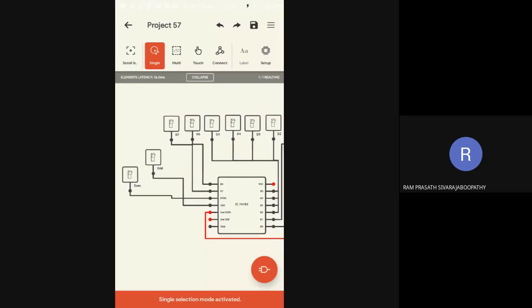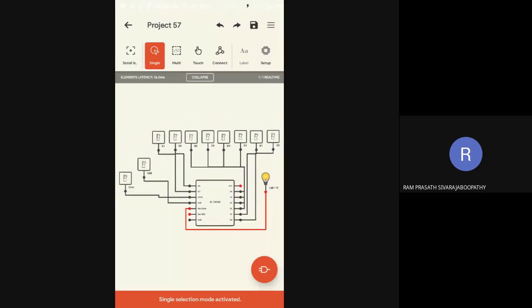Fine. So now we are going to call it a parity generator. What did we say a generator must do? Configuration: even must be 0, odd must be 1. Now this particular output along with the message always produces even parity. Say for example, I have given 3 random data inputs, 111, correct? So what should the parity generated be? What about the parity bit that must be generated? There are an odd number of ones. So the parity bit must be 1.